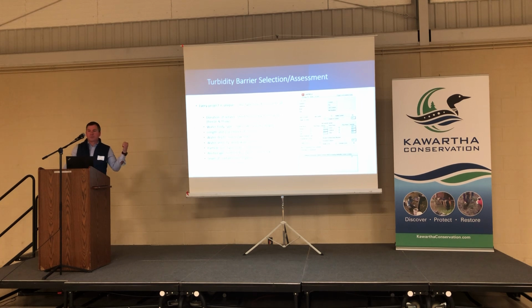The Gaspé project was in a tidal area, so every day that curtain would rise and lower almost to its full extent. So understanding what those conditions are will help us make a better suggestion on the right product. Water velocity, so your flow rates. Wind and wave action. Is this in an open lake, for example, Lake Simcoe or Lake Ontario, where it has very little protection, or is it in a protected pond?